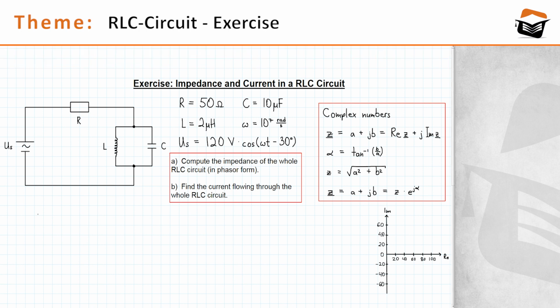The equation for the impedance of that subcircuit will be 1 over underlined X sub LC. The LC reflects the fact that the subcircuit consists of a capacitor and an inductor. And the underlining of the X means that we are working with complex numbers. I will not be mentioning the underline verbally, just for convenience. But I will write it down, of course.